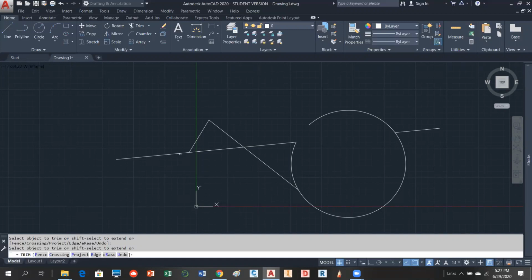Okay. All right, so very useful tools. Now, what else have we used to do trims and extends with? What other command? Fillet, and also the one we looked at today was chamfer, okay? Those will also do that, but they're not going to be as flexible as the trim or extend, okay?